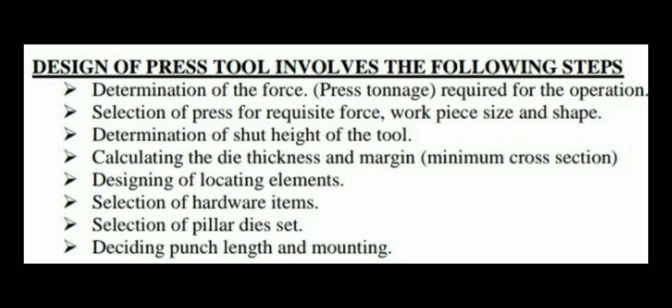One is determination of forces, which we already discussed, that is the press tonnage required for the operation. Then selection of press for requisite force, workpiece size and shape. Then determination of shut height of the tool. Then calculation of die thickness and margin, that is minimum cross section.